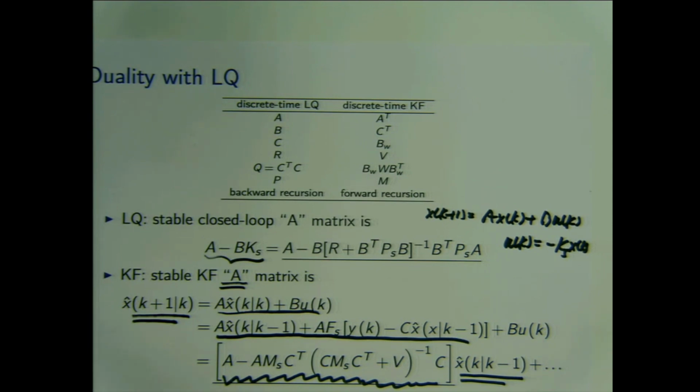But I'm only estimating the states, and an unstable plant can be stabilized by a controller first. An unstable plant doesn't mean the state will blow up, right? So the answer is that the Kalman filter applies to unstable plants as well. And that's actually the power of the Kalman filter, right? The states you're estimating shouldn't blow up at the beginning to start with, right? I think we almost finished talking about that.